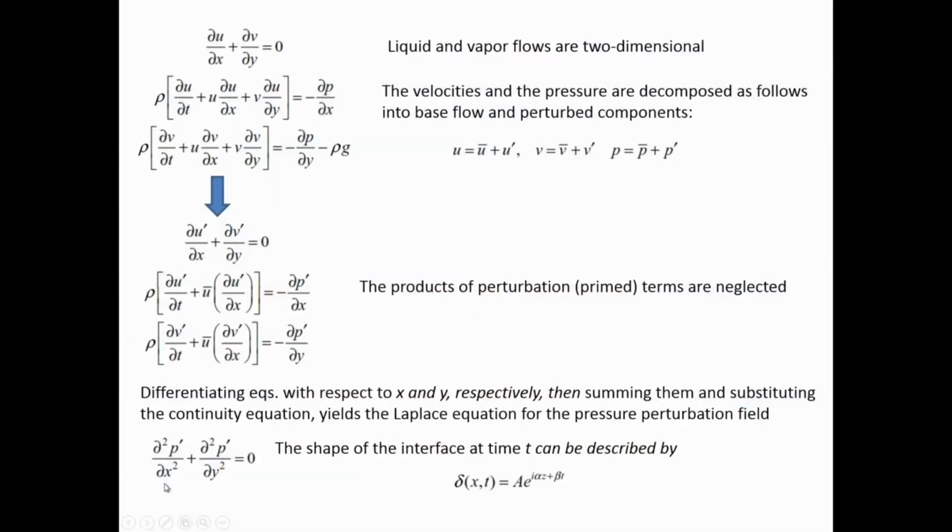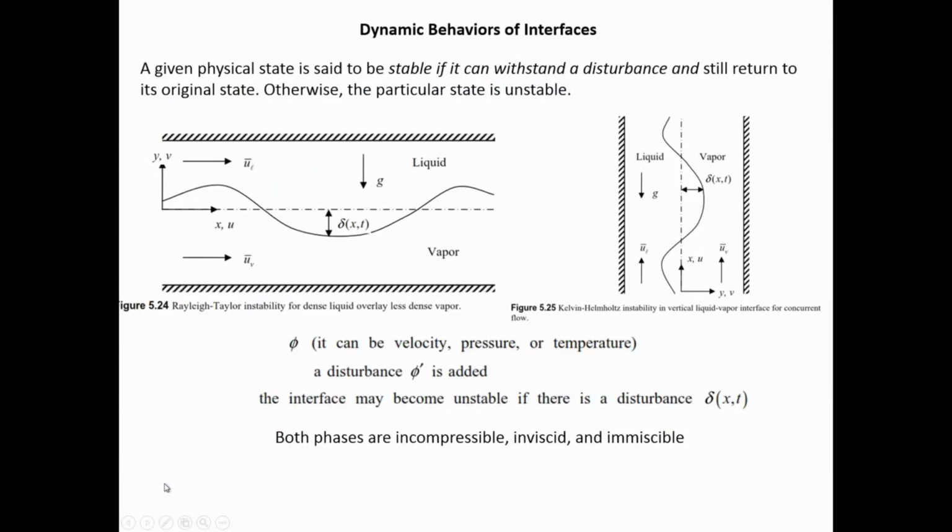Just now we established that there are two conduction terms, basically, that are equal to the mass that evaporates from one phase to the other, if we neglect all the kinetic energy terms. It is very normal practice to neglect the kinetic energy terms, because the other terms are so much more significant. But before doing that, let us do the dynamic part of the interface, which is what we are going to do in the next few slides.